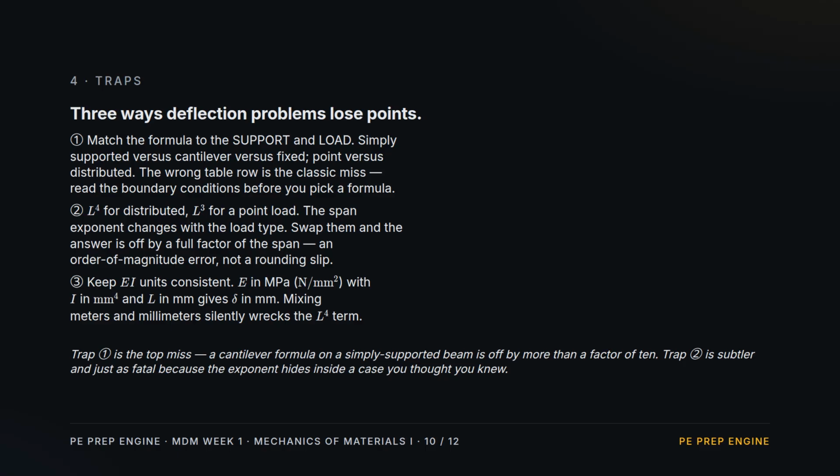3. Keep the EI units consistent. Modulus in megapascals, inertia in millimeters to the fourth, span in millimeters, and the deflection lands in millimeters. Mix meters and millimeters, and the span term quietly falls apart.